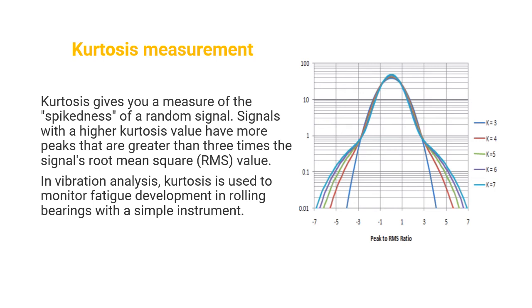So don't get overwhelmed by these terms or by these curves, because we need to only know that there is a technique called kurtosis measurement, and kurtosis measurement is mainly used to monitor the fatigue development in the rolling bearing. That's all we need to know for the CMRP exam and also for basic vibration analysis training.